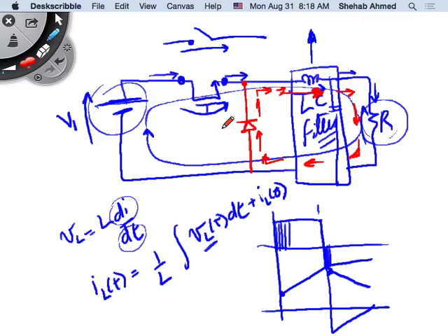And we can live with that in a low voltage circuit, no problem. It's not like it's not allowed. You can live with that in your house. It doesn't bother you. But in a power electronic circuit that's inside this thing, I cannot, because there are other power electronic devices around it. If it keeps arcing and breaking down the air around it, it may ruin the rest of the circuits. It will burn the board. It's not something that you can handle safely. Versus a switch that's inside the wall, fine. If it arcs a little bit and the contacts erode at some point, you change that. It doesn't really bother you. So in power electronics, we created this alternative path for the current to flow through this diode.